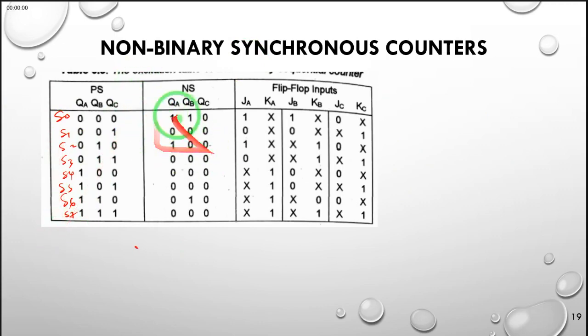But then we know that when we are moving from S0, we are going to S6. But if we find ourselves in the lockout state S1, we go back to the default state, which is S0. And if we find ourselves in S2, we go to S4. But again, when we find ourselves in another lockout state, we go back to the default, which is S0. Again, our normal flow resumes, but if we find ourselves in a lockout state, again, we go back to S0. So that is how you do the design.